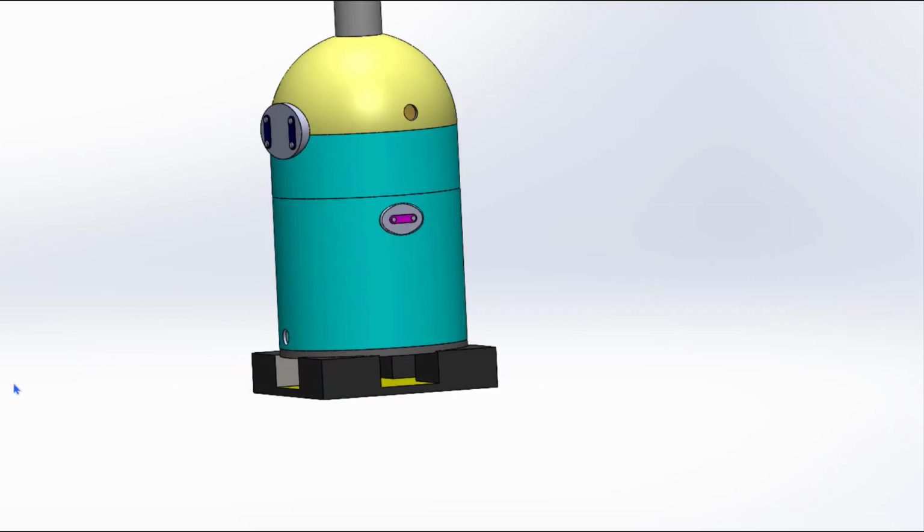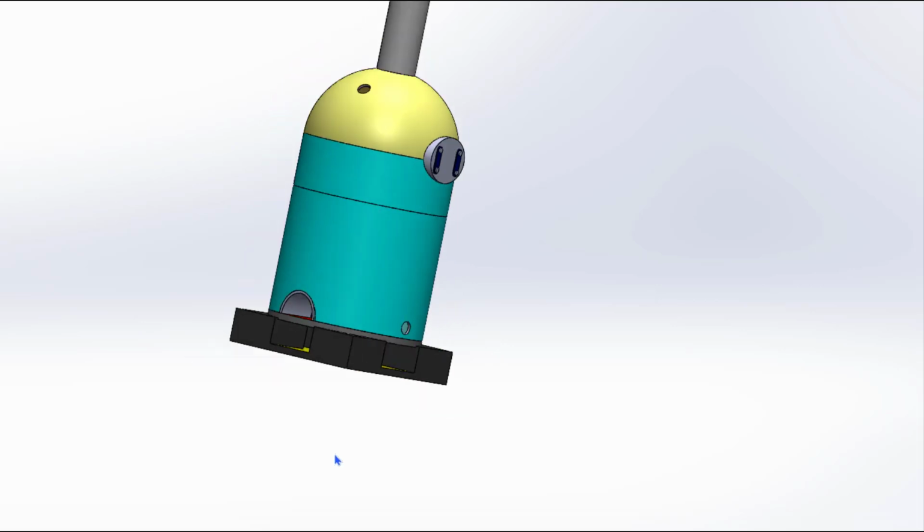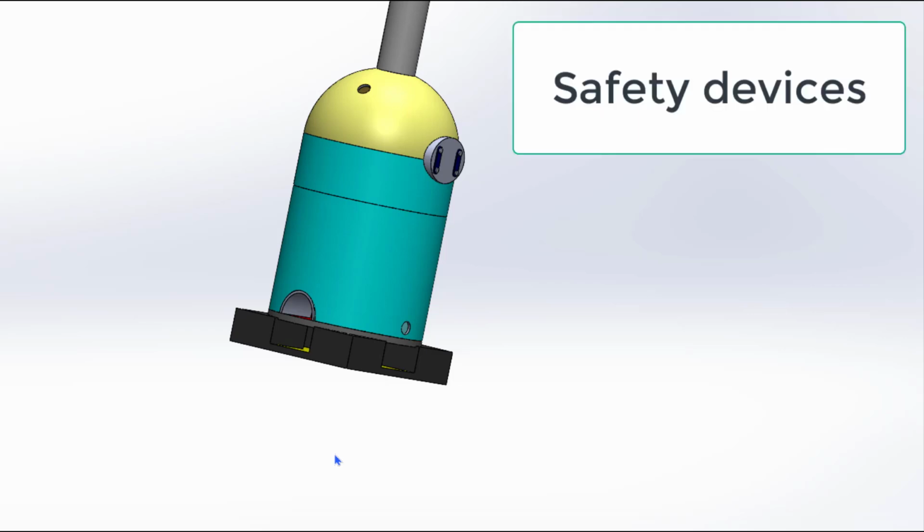So simply these are the things, but the safety of a boiler is a very essential thing, because a boiler works at high pressure and handles steam and hot water. If the boiler explodes due to high pressure or because of a low water level inside, it is a catastrophic failure of the boiler.